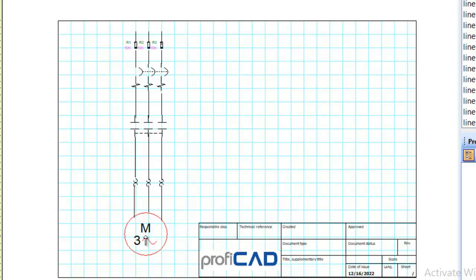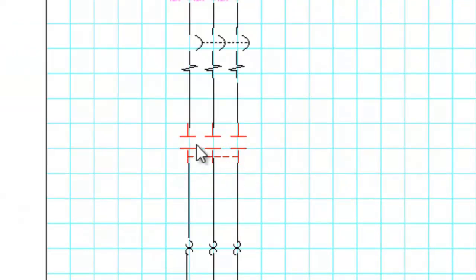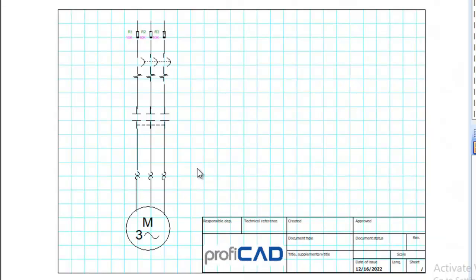So we are going to look at a very simple control circuit, a circuit that will control this particular motor. So what we need to do now, since the contactor is open, after we have closed the circuit breaker, it means that we have power at the input of the contactor. So we need a control that will help us to close the contactor so that power will flow to our electric motor. Then we also need to incorporate all of these overload devices into the control circuit so that they will be able to protect our circuitry.